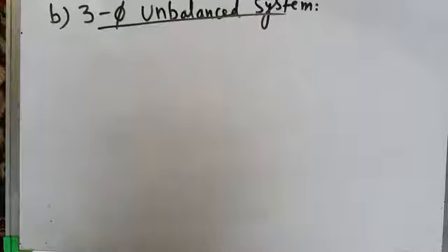And the third main cause is arrangement of different loads on three phases. I mean, if you have a three-phase four-wire system, star connected system of course, and this system is feeding single-phase loads, then you are not uniformly distributing single-phase loads on all the three phases. So different loads are put on different phases, so that will cause unbalance in load currents, and that will result in unbalance in voltages.